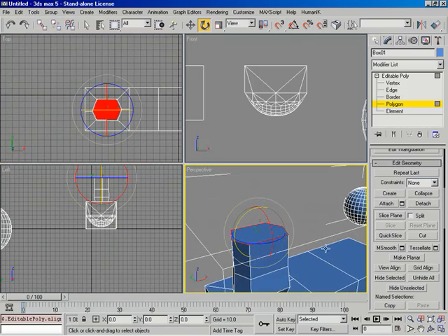Do you know exactly how it works there, Zach? Well, in an orthographic view, what it's going to be doing is just translating your vertices so that they line up and they are planar with the selected orthographic view. Exactly, and the problem with that is there's a good chance it'll change your shape. Yeah, it'll alter your shape just a little bit because all it's doing is really sliding those vertices. Exactly, so that could deform what you have selected.